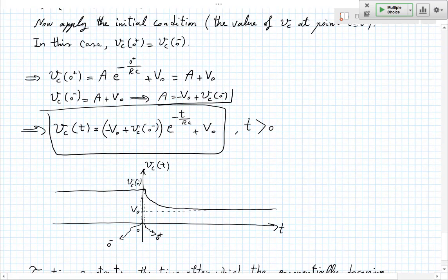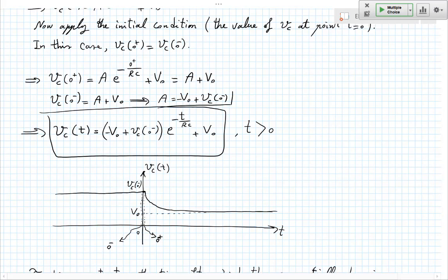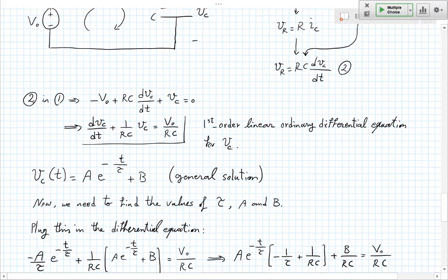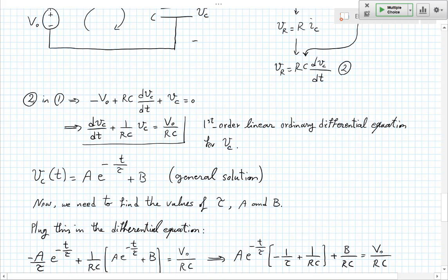And the concept of initial value and final value is something that, again, you would readily see from this equation. So the initial value, if you're talking about this Vc equals a e to the minus t over tau plus b, well, at time t equals 0, this initial value, in this case, is a plus b, because the exponential of 0 is 1.